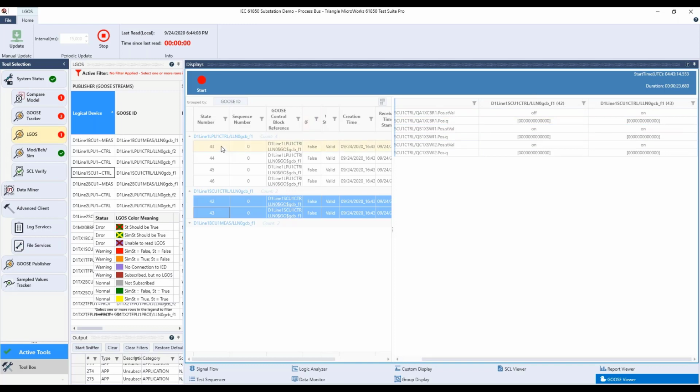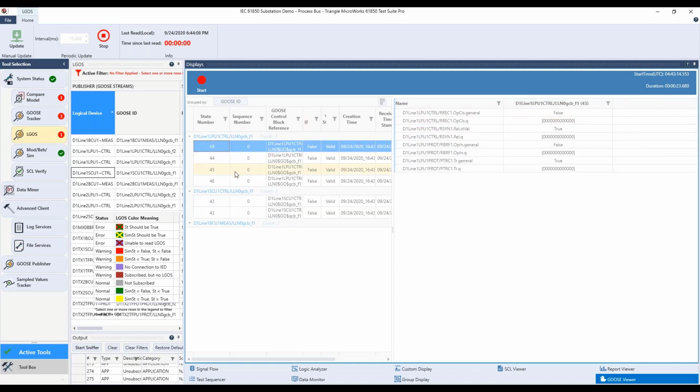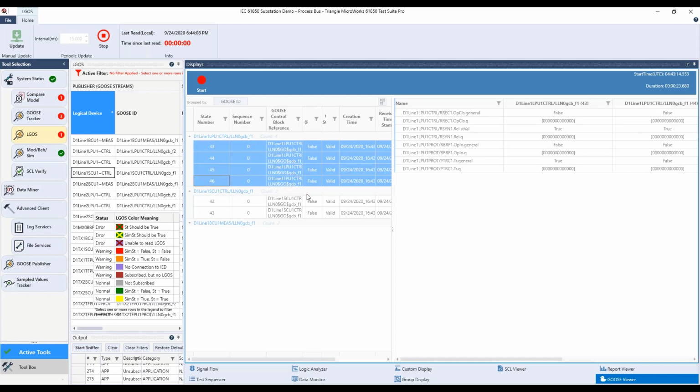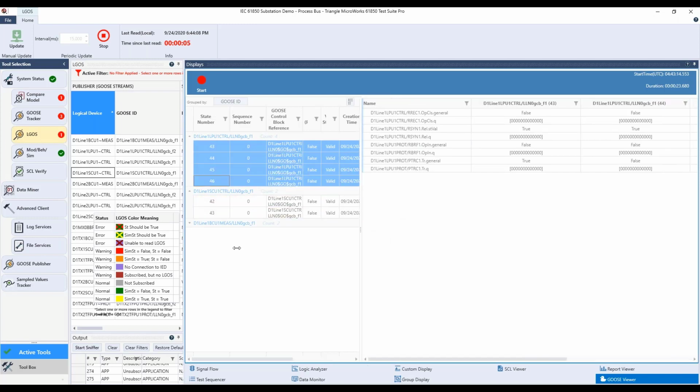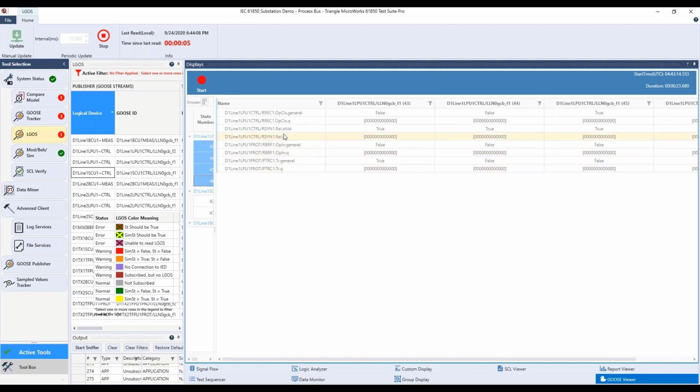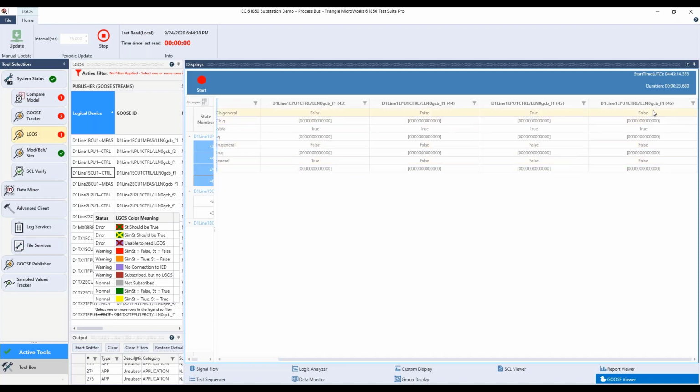And if you look at the line protection, you can also look what happened here. When we started, we also have the release from the synchro check there, which is always true in our simulation. But we then had in the first message the trip, that was true. The second message was when the trip went back. Then we had the op close from the recloser that was becoming true, and that went back again. So that's the expected interactions of the signals.